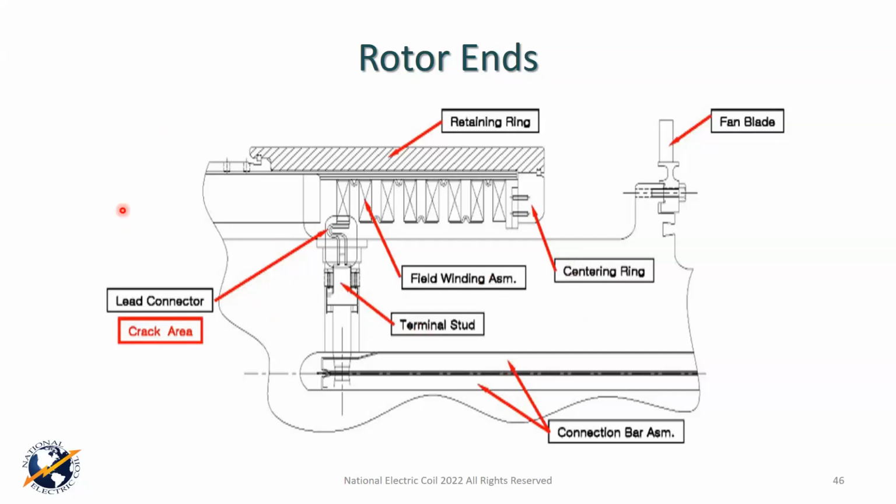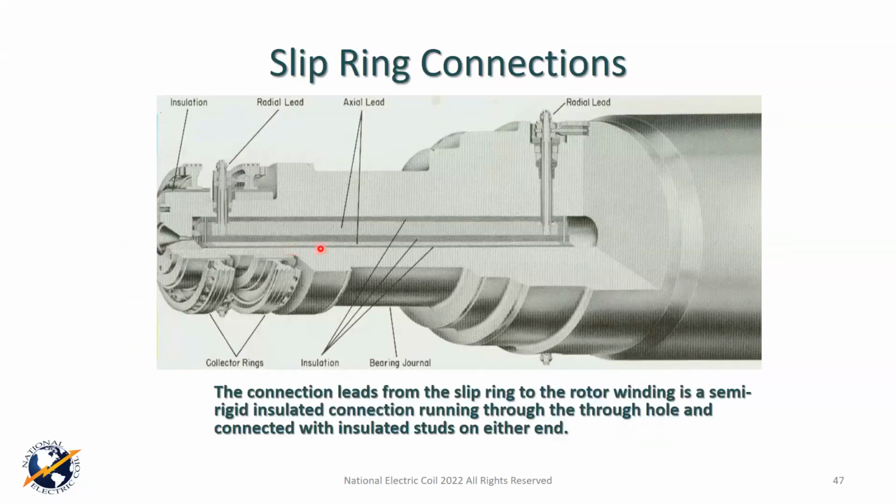This is your rotor body up here. This is the end going out towards the bearings and so on. Got a radial fan up here. In this case, they're bolt on. So that's what we got. The thing I want to talk to you about is we're going to talk about pole-to-pole connectors, talking about coil-to-coil connectors, and we're going to talk about main lead connectors here real quick so we understand.